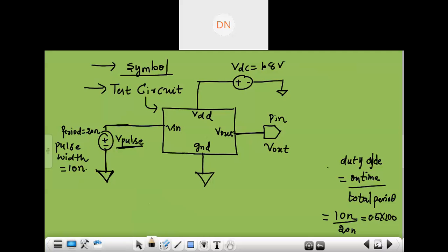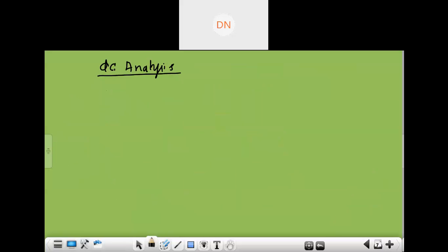Instead of doing that, you have a method in your Cadence tool to perform DC analysis. Here, Cadence will ask which parameter you have to use for DC analysis. What is the component you have to use to make DC analysis? You have the options there.